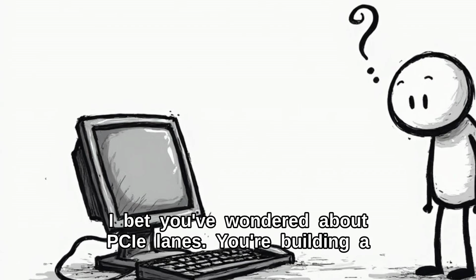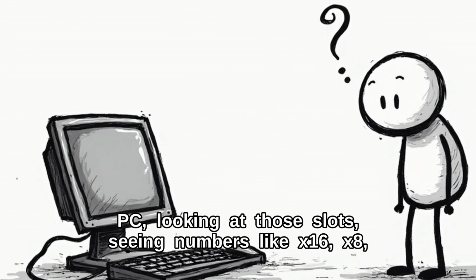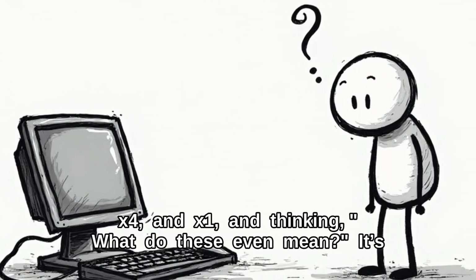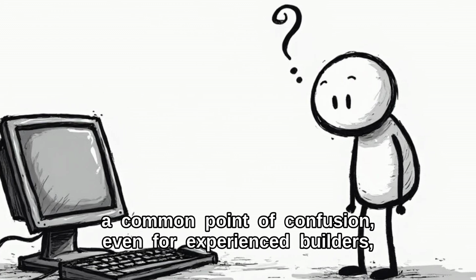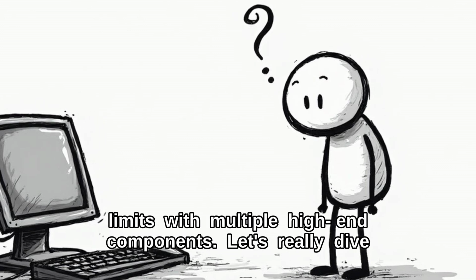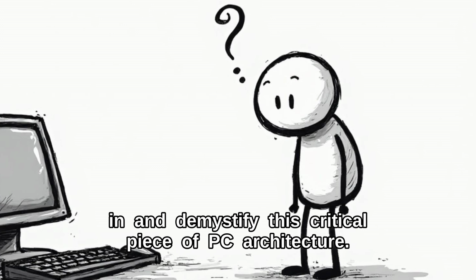I bet you have wondered about PCIe lanes. You are building a PC, looking at those slots, seeing numbers like X16, X8, X4, and X1, and thinking, what do these even mean? It is a common point of confusion, even for experienced builders, and it is something that can genuinely impact your system's performance, especially if you are trying to push the limits with multiple high-end components. Let us really dive in and demystify this critical piece of PC architecture.